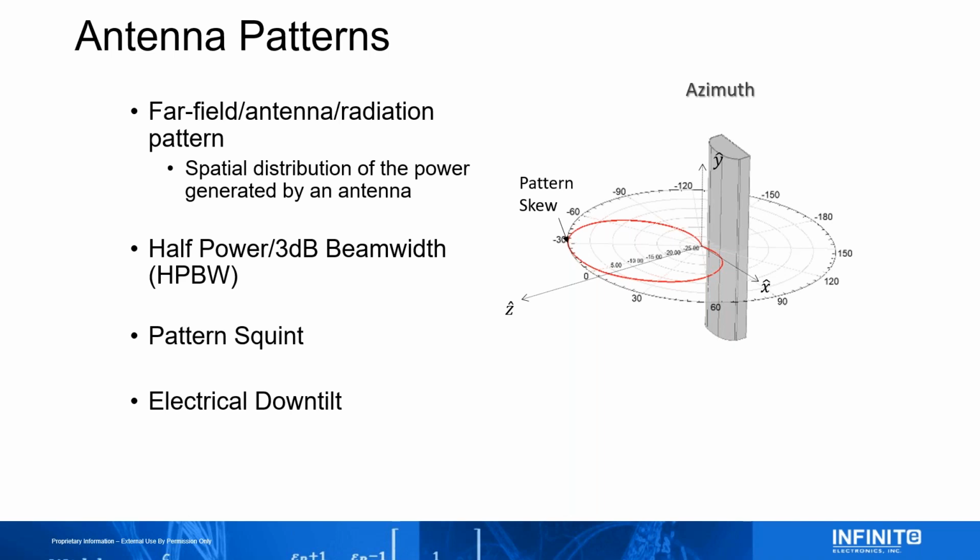That means that even though your antenna or sector is pointed forward, the beam actually points a little bit to the left or right in the azimuth direction. It's usually only a few degrees, less than 5. In severe cases, it can be 10 to 15. But you need to know that because in the real world, when you're doing the coverage, you're going to see that little bit of asymmetry in the coverage on the ground.